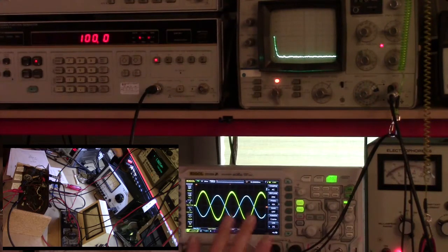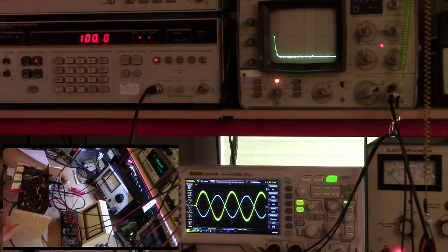But the point is right here at 1K, we're putting in 100 millivolts of signal, and we're getting out 20 volts of output voltage, which is good because we need to drive the output tube, which is a 6F6. We need some high voltage swings to actually drive that up into getting its output power. Let's measure the frequency response.